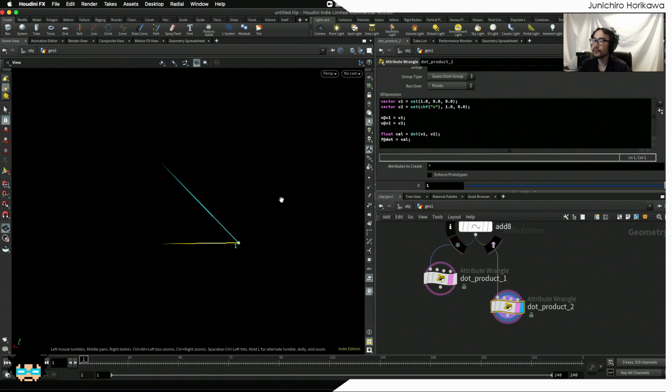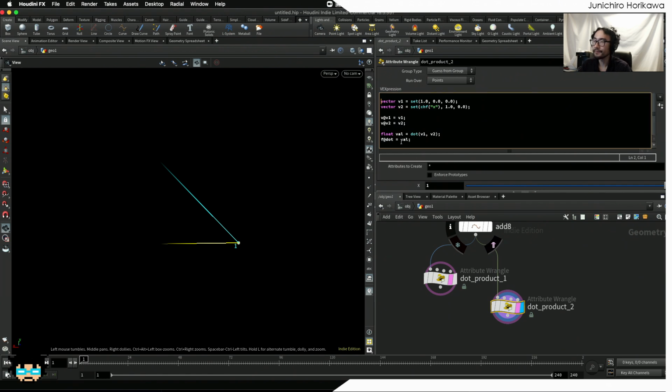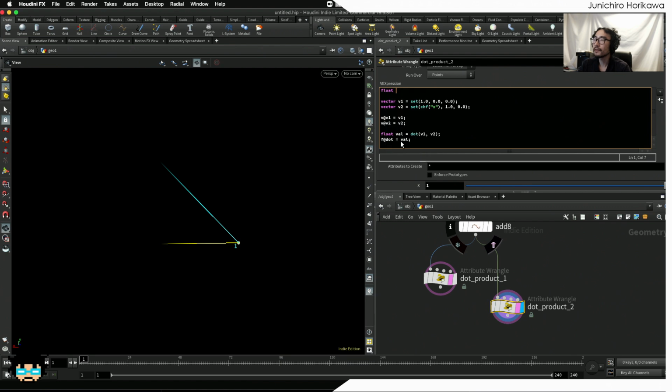In order to create the rotation of the vectors, I'm again going to use trigonometry. To do that, we need an angle value first. So I'm going to create an angle value with a CHF and multiply by pi multiplied by 2. In this case, you'll be able to have a value between 0 and 2 pi, with this angle value being in the range between 0 and 1, meaning you have a rotational angle value between 0 and 360 degrees.